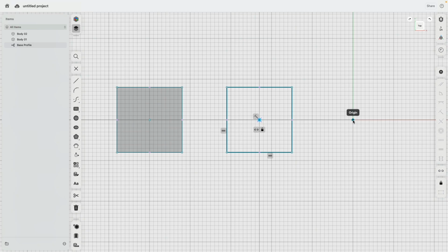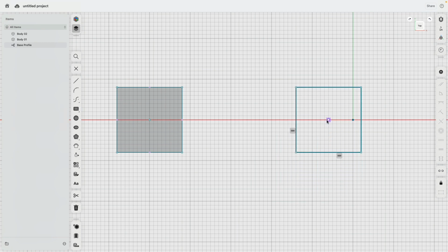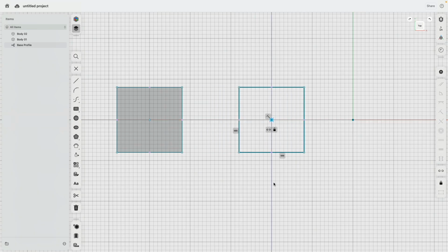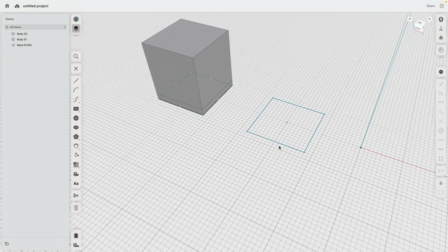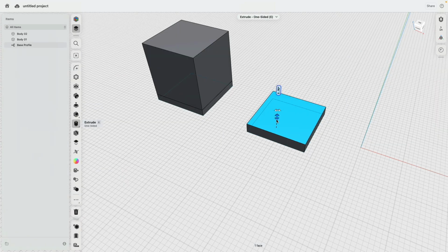You see this is locked via a coincident constraint to this midpoint. If you select the constraint, delete it, and this one can freely move around. If I go back onto the axis, it locks it onto it automatically, so I can just move this around. Now this is the way how I start sketching and then later move sketches around and build my parts or reposition everything. Sometimes you design and then you need to clean up your scene.